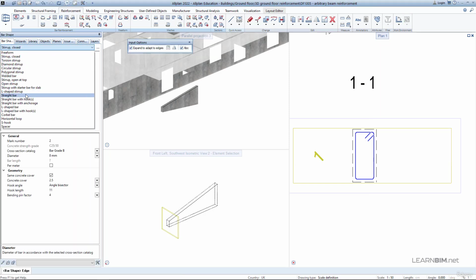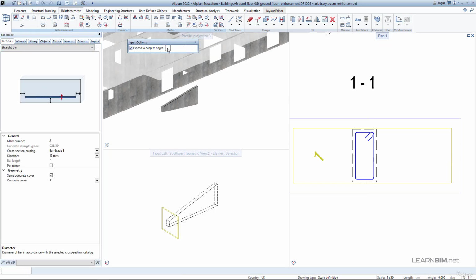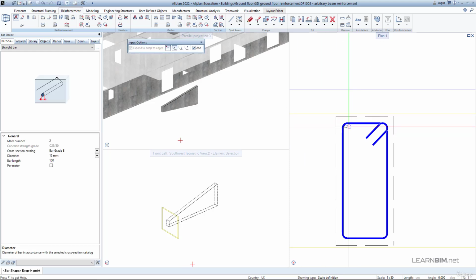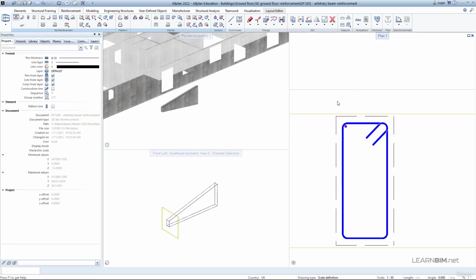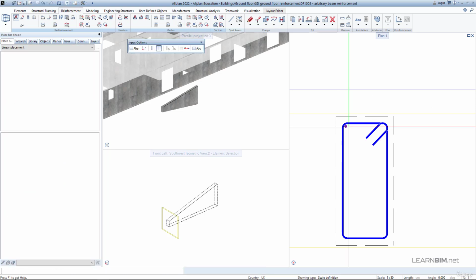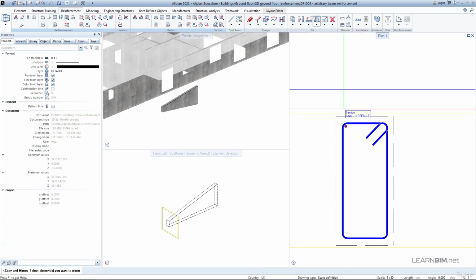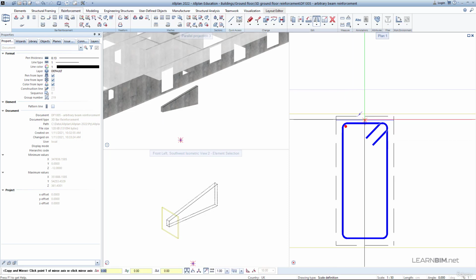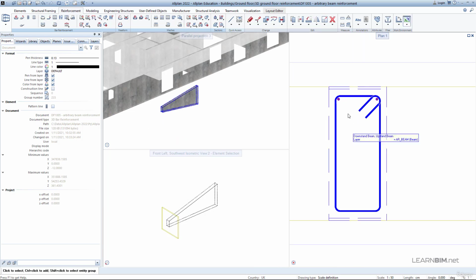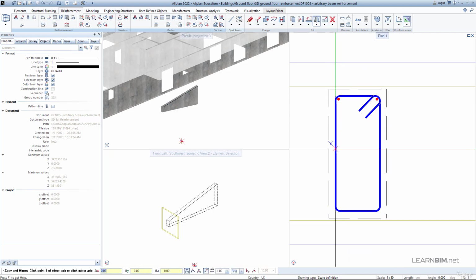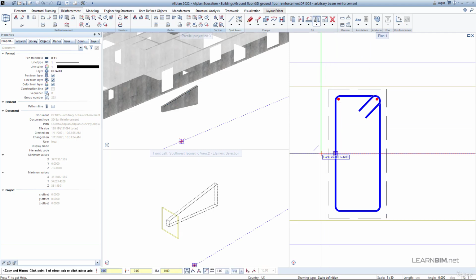Choose Straight Bar Type. Activate the option Straight Bar as Point. Place bars as points in fillet. Exit all following commands by pressing the Escape key several times. Copy and mirror the straight bar on the other side of the stirrup. Now copy and mirror the two straight bars in the lower layer of the beam element.